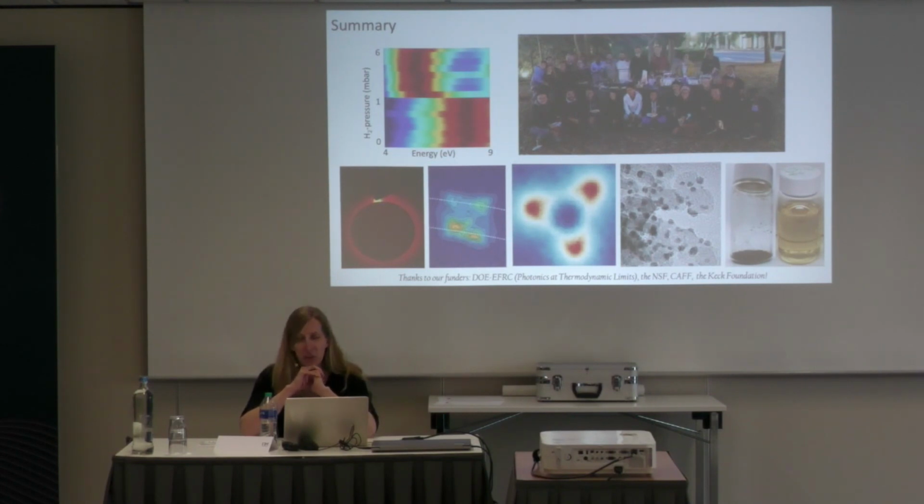Yeah, really great question. I think the reactors being developed for plasmon photocatalysis are inspired by flow reactors that are often used in the pharmaceutical industry, where you can think about a thinner capillary tube that gets packed with your catalytic material, but then wound almost like a coil or a helix, and then you can wrap LEDs all around it.